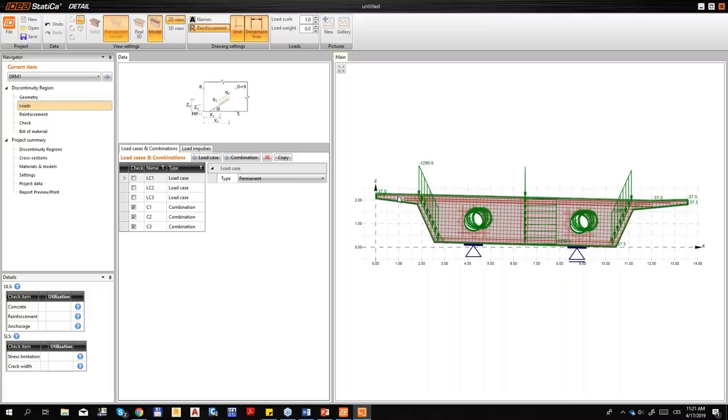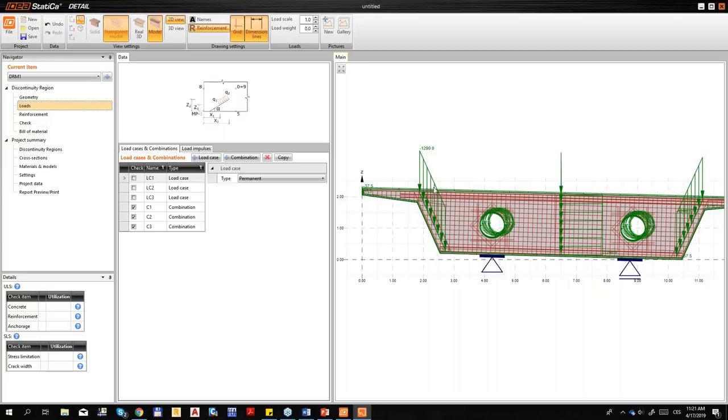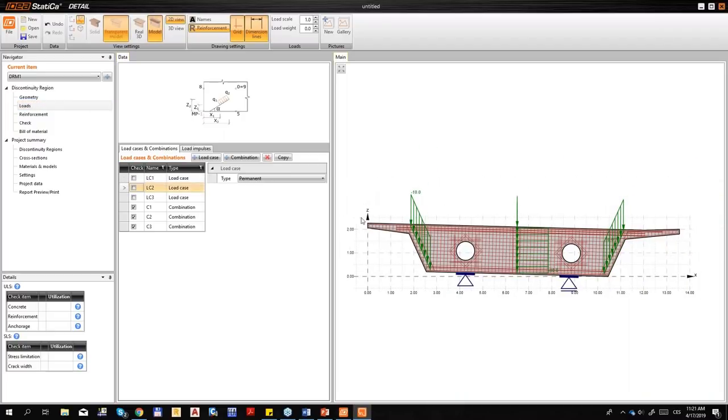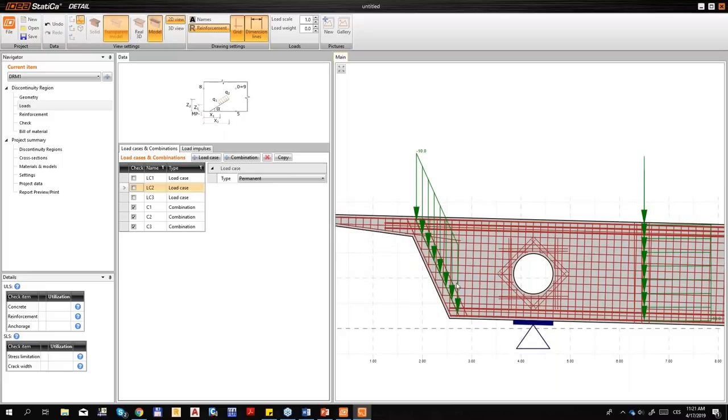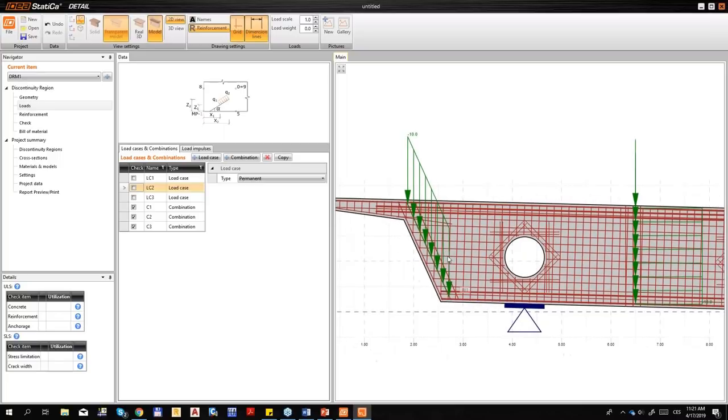So we prepared for you some free load cases. The first one is the basic self weight of the structure, which is interpreted as a line load in the wall or in the center line of the cross section, which is interconnected with the mass of the diaphragm. The second load case is some superimposed dead load, which is as well imagined by line loads.